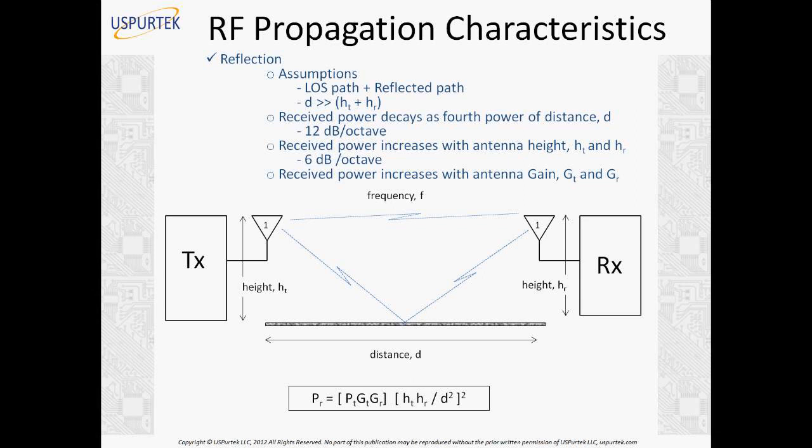You have to increase both antenna heights. But of course, even by increasing one antenna height, you will get very good results. Usually it is very easy to increase the antenna height of the transmitter at the time of installation. But if you have a handset in your pocket, you cannot increase your own height actually. Whatever height you have. You could rise to the rooftop to get a call, but that is not a very practical scenario. So really we are talking about increasing the antenna height of the transmitter here, the cell tower. And it makes more sense that way. But of course, it's a fact that if you go up in the building, your signal will be stronger. If you go up to the rooftop, your signal will be stronger. Okay.